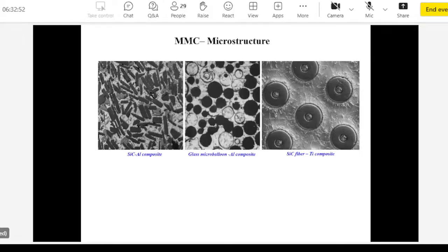in composites. There could be defect forming because if you're pressurizing like this casting, if you're making fibers, the pressure application might kind of bunch up the fiber in certain areas instead of uniformly distributing them. So you can have these kind of channeling effects. So you have to have some special methods, things like fugitive binders that can hold fibers in place.